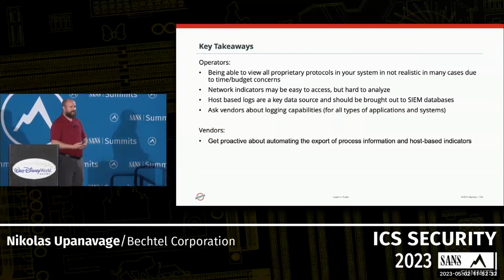Proprietary protocols in these systems are very challenging. There's lots of vendors and tools out there that talk about coverage of proprietary protocols, and in our experience, we've seen good and bad. And a lot of times, even if it is covered, you're not really getting a lot of the context you need from the protocol. So you might not get all the data about what logic was loaded, what blocks were modified, was the set point changed, things like that, just due to the nature of how the proprietary protocol works.